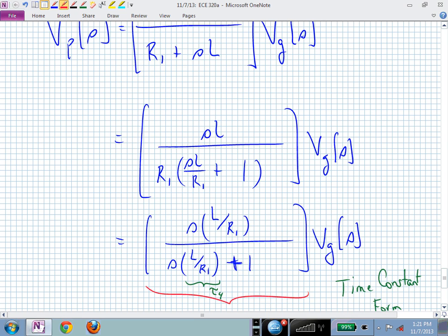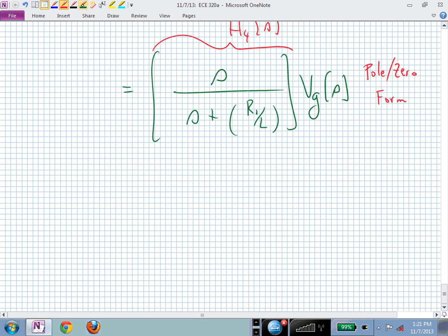What's this going to be shaped like then? In terms of frequency behavior, that numerator, 0 at the origin, that's a finite 0, a thumbtack right at the origin, right at DC, and then we climb up, don't we? And instead of going outside, we go flat. And this happens where? That's our break frequency, which in this case is R1 over L. And we just had a 0 at the origin, so this is going up at plus 20 dB per decade.